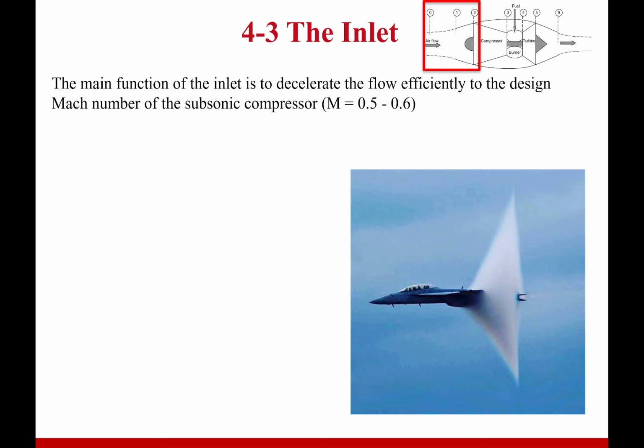Okay, so what is the purpose of an inlet? Well, an inlet is all about decelerating our flow, okay? And we're doing that because we want to get it down to the Mach number that our compressor actually functions at, which is typically around 0.5 to 0.6. So we've got to slow down that flow.